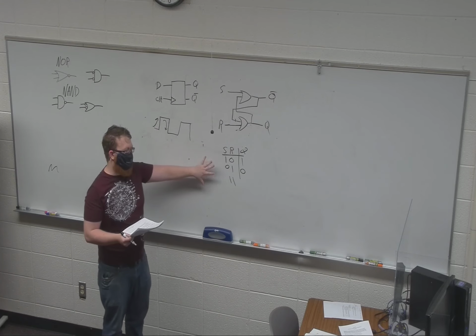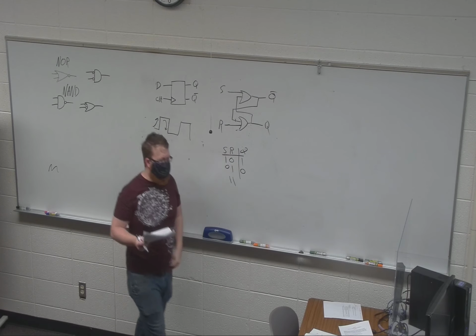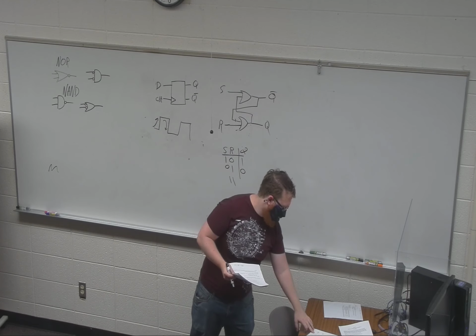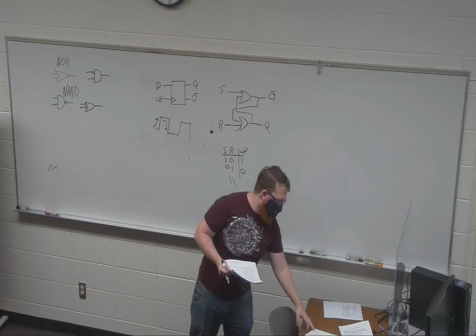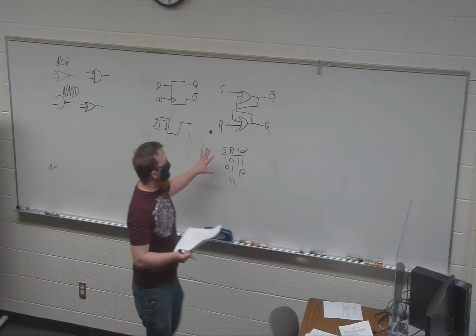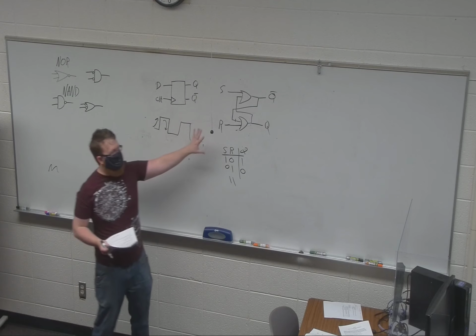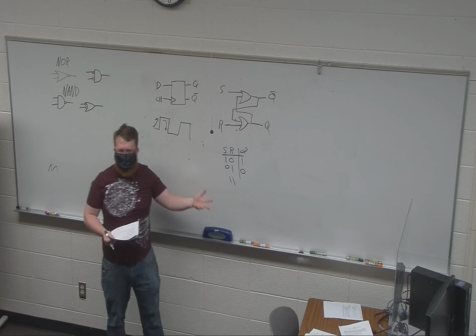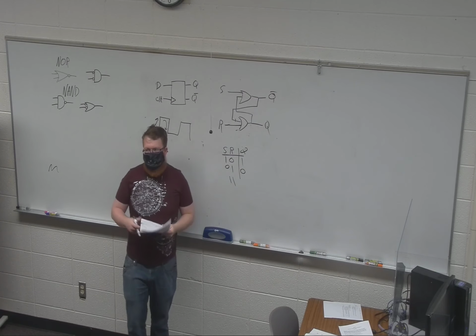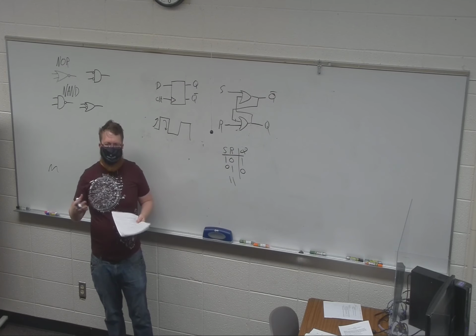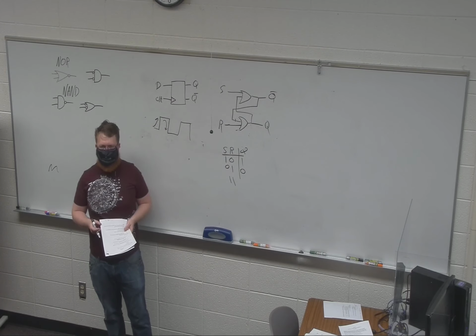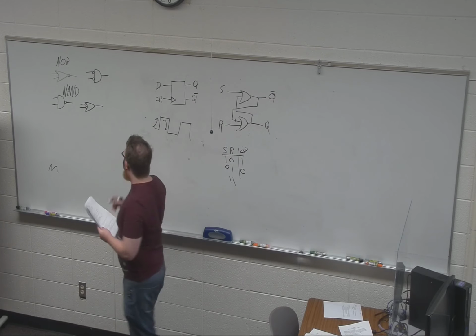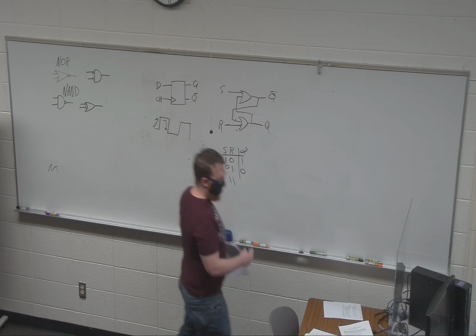Now this is where they start doing gated latches, which I think they have an example in, but I'm not going to walk through specifically. But this set reset idea is a very useful thing because it holds memory. It remembers what it was, but it can have an issue. And we want something that remembers it, but we don't want all of these issues. So does anyone remember which one of the more robust flip-flops is? So the JKs, right? Those are very flexible and useful flip-flops.